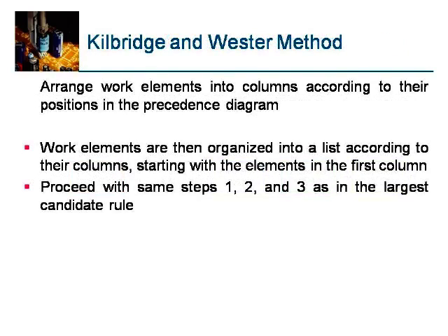That's how the physical layout of workstations and assignment of work elements to the stations is done according to the largest candidate rule. If you see here, the elemental time at each station is supposed to be equal to 1, but it is not because of total variations. Total time for this is different, for this is different. This is unavoidable. So if the total work content time is 4 minutes, here there is going to be a delay because the total number of stations is more here.